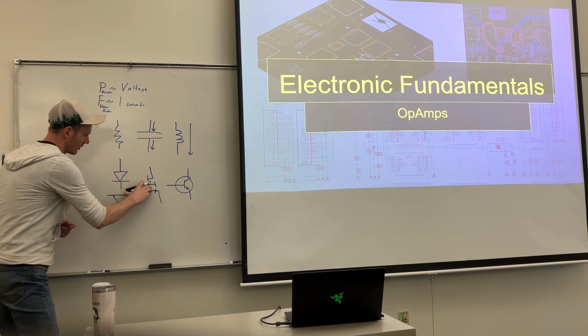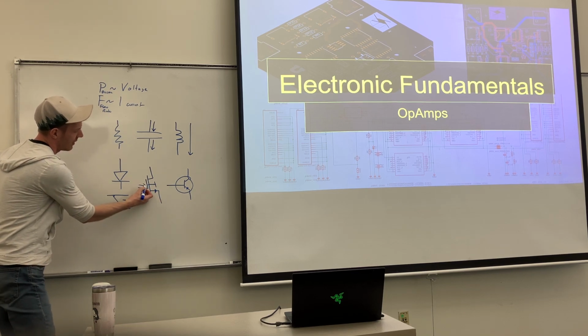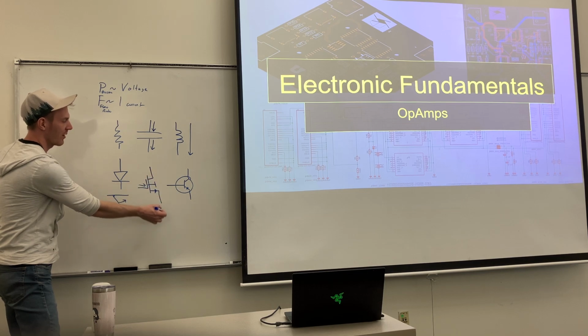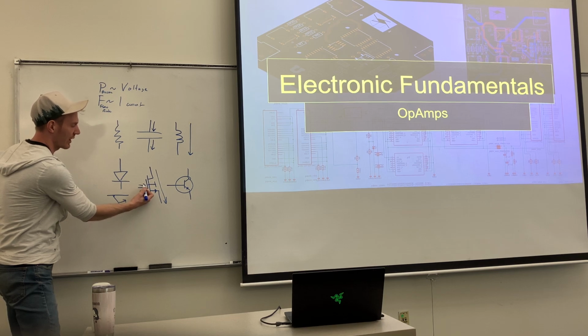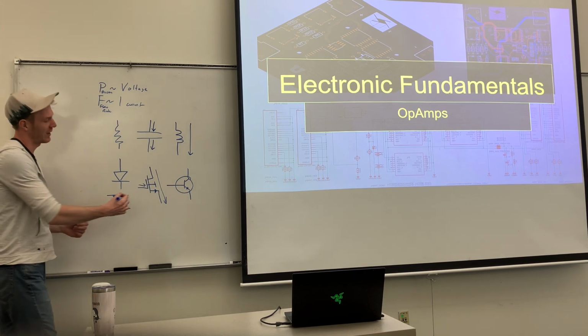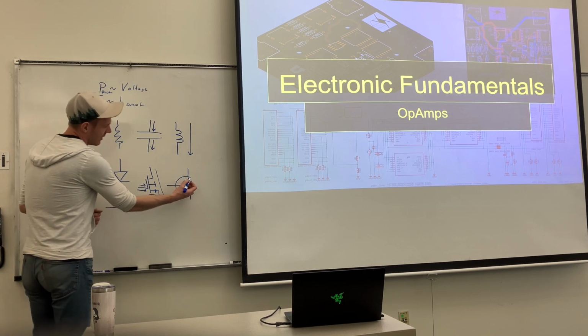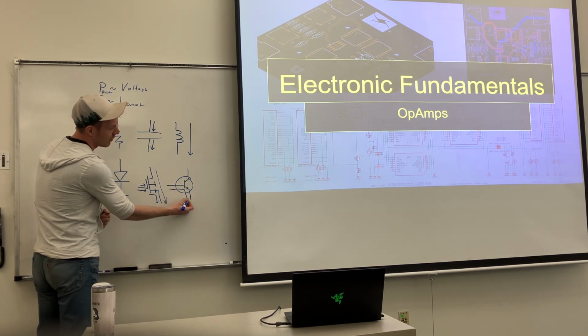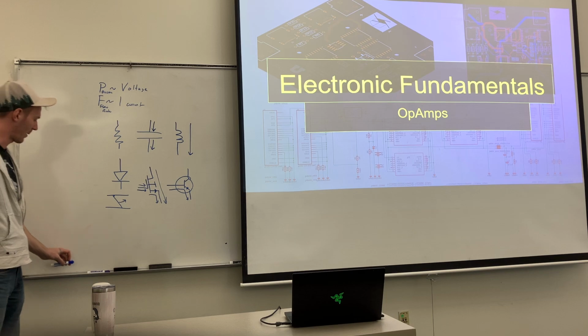Actually, I drew this wrong. These ones are field effect transistors, so your input voltage determines whether or not current is allowed to flow through. Because there's not an actual connection here, it has theoretically infinite impedance. Impedance is like a fancy version of resistance that has some other stuff incorporated that's not really important here. What you should take away is that you can have a signal which doesn't require current. It is voltage driven. For bipolar junction transistors, you do have a path for current. Current is actually what controls the throttling. That's the important part to get out of that.